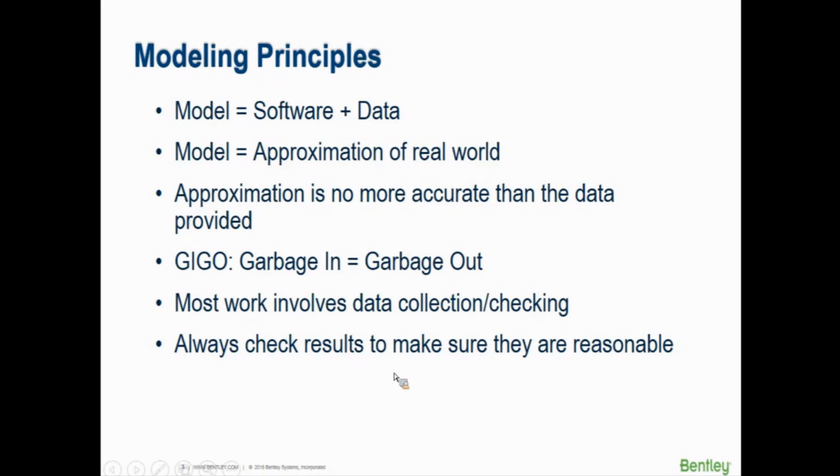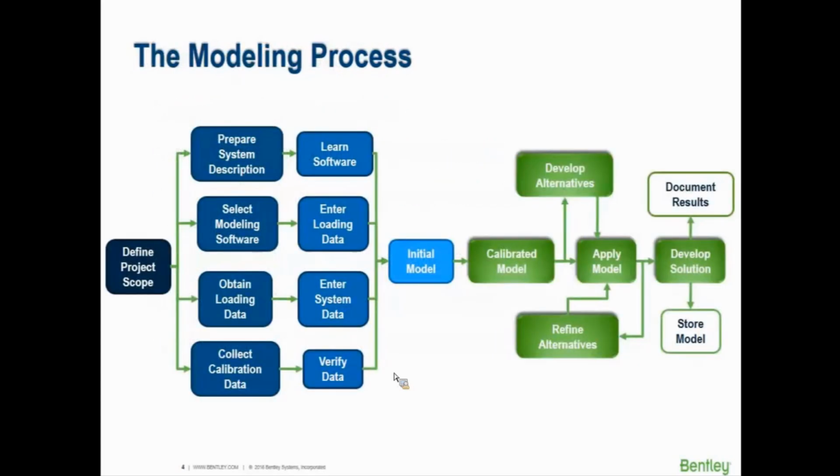You're going to spend a lot of your time checking results and checking input data. It's fun to do the modeling, but the hard work comes in verifying data, verifying the piping network, verifying C factors, verifying pump curves, making sure all of that's right, because it's so easy to put the data in, but you've got to verify that it's correct data.